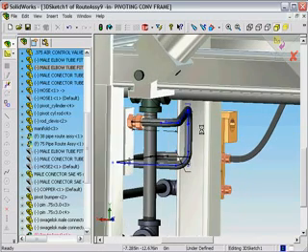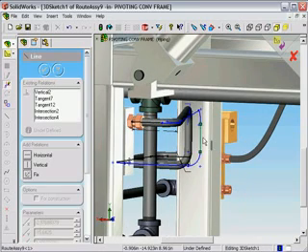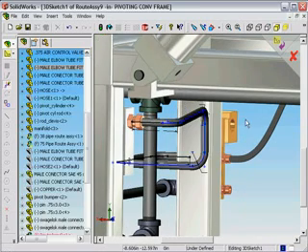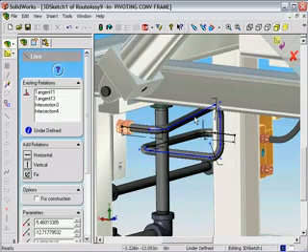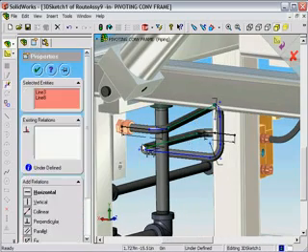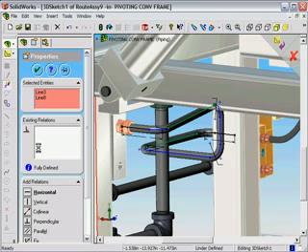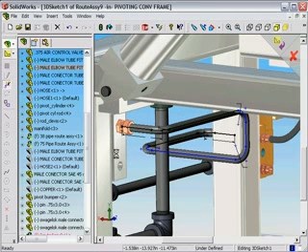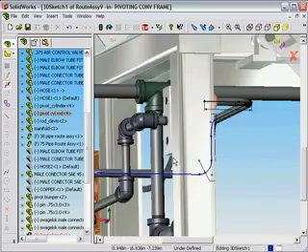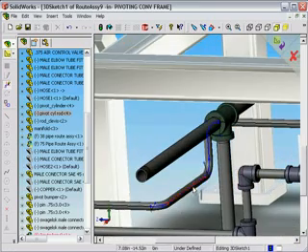Because SolidWorks Routing is sketch space, it's very easy to make changes simply by dragging and dropping. You can reorient the route and change the tube. SolidWorks standard sketch relationships are available. To add design intent, in this case we'll add a parallel relationship in order to keep all our bends at 90 degrees.